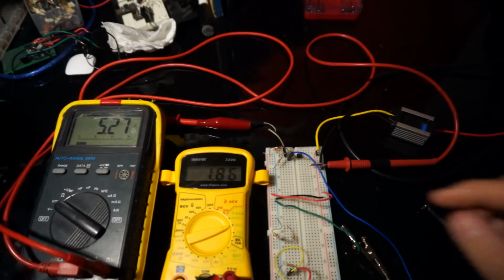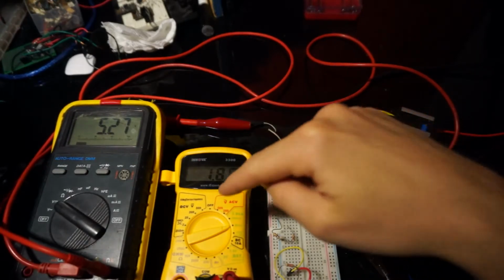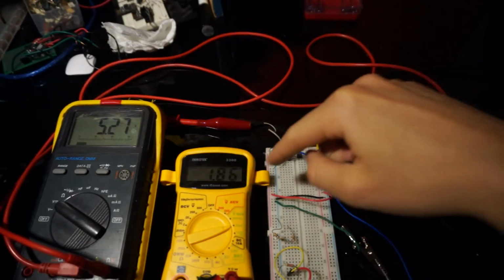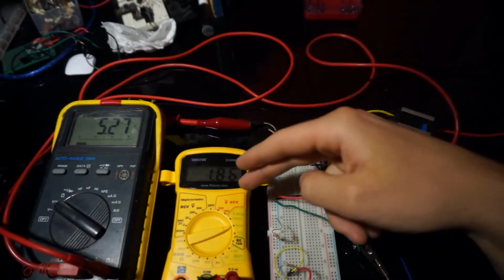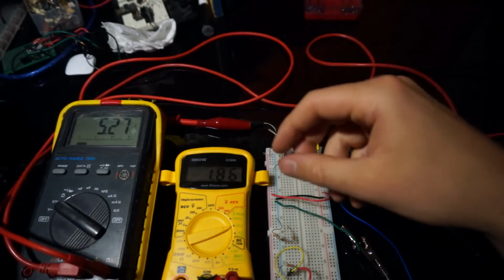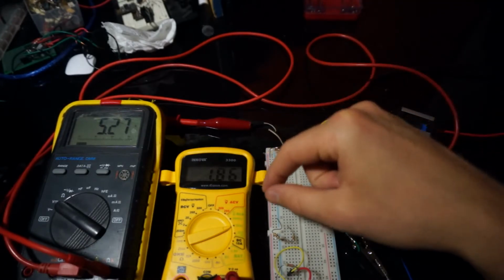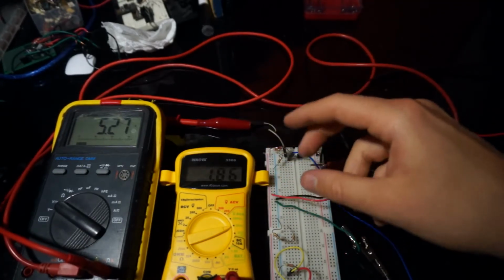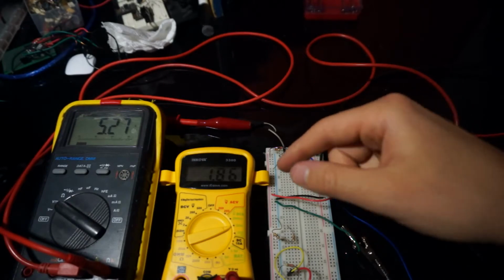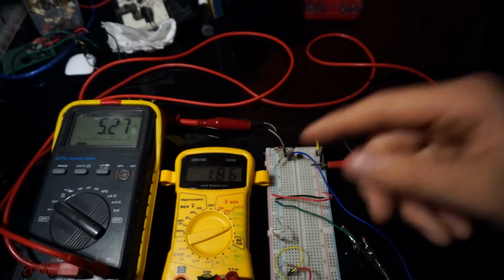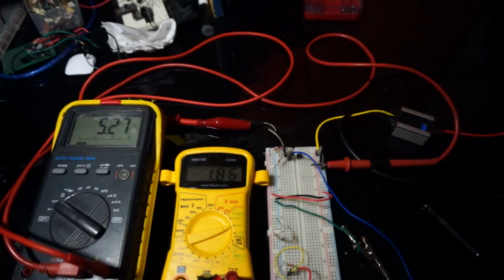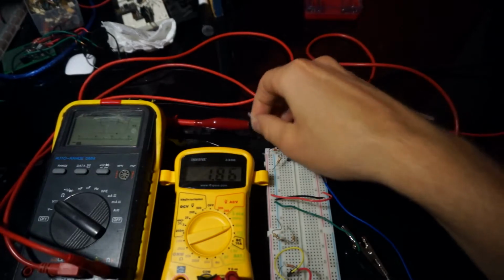So let's go ahead and build it and check it in reality. Okay, so here it is, all wired up. In this meter we have milliamps. I just have this as the device under test here. You know how these guys test current: it's just a very small load that they measure a small voltage across. So that's the device under test, and this guy is the voltmeter that we're going to stick around in different places. But this is going to stay put.